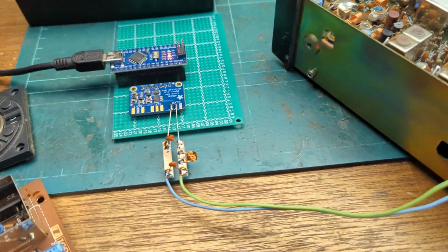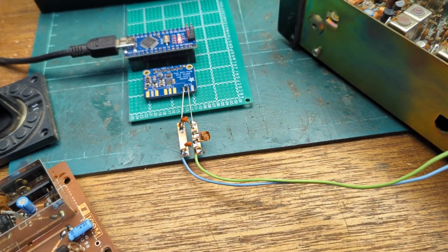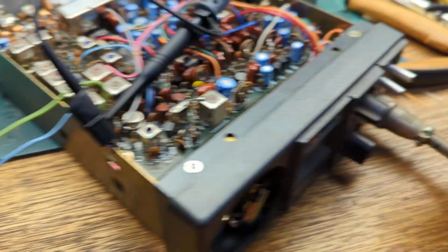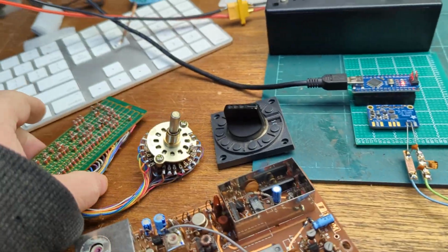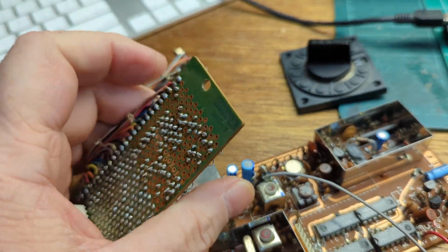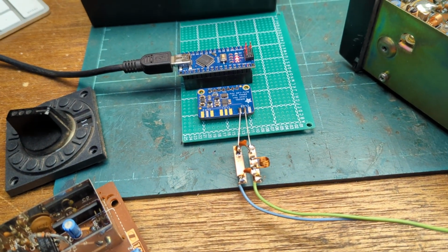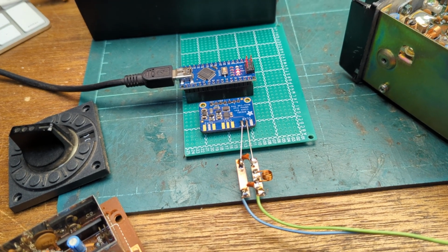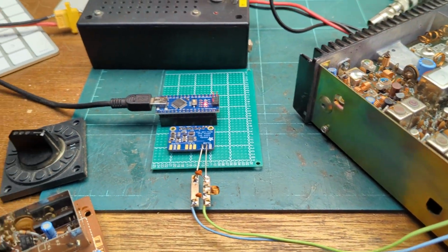And so in many respects, this one's actually simpler than the 22A because I only need to have one LO. Basically, the switch on the front that does the duplexing is just a pin that ends up on this board here, and it just alters the 600 kilohertz for the PLL. So all I have to do is pick up that signal, feed it into this, and then whenever that switch is in up or down or in the middle position, I just offset whatever the set frequency is for receive or transmit, because that's effectively what that does.